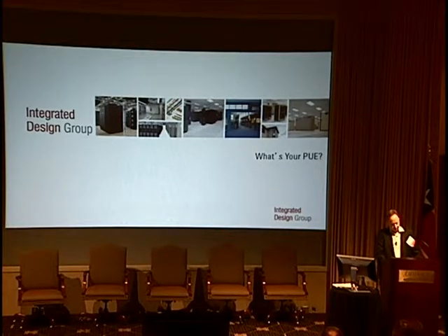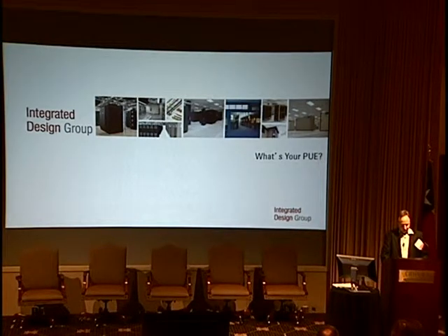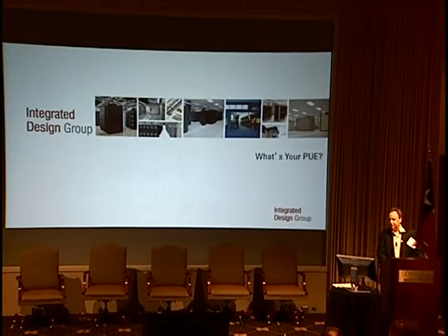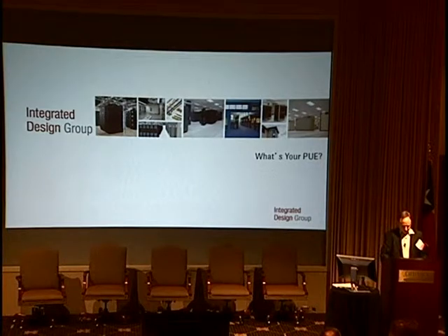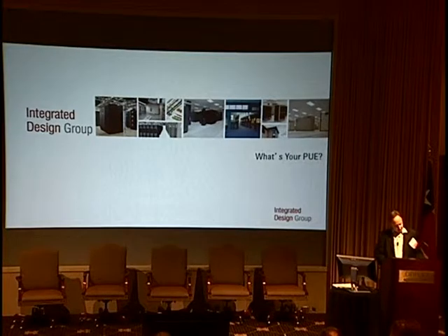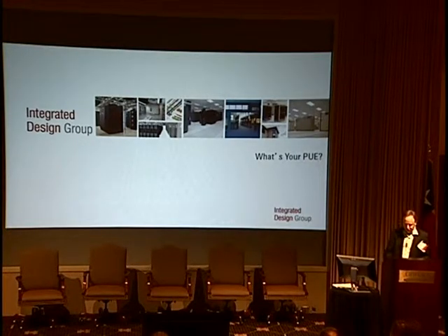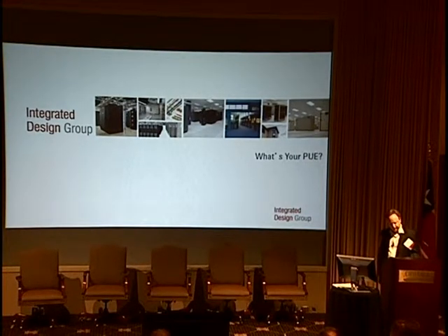It's well known that cooling systems utilizing some sort of economizers are most efficient, and we can show that IT space operating conditions allowing larger temperature and humidity ranges increase economizer operating hours. This results in significant PUE improvements and operating cost savings. I'm sure that most of you are familiar with PUE, but I'd like to quickly define what it is.